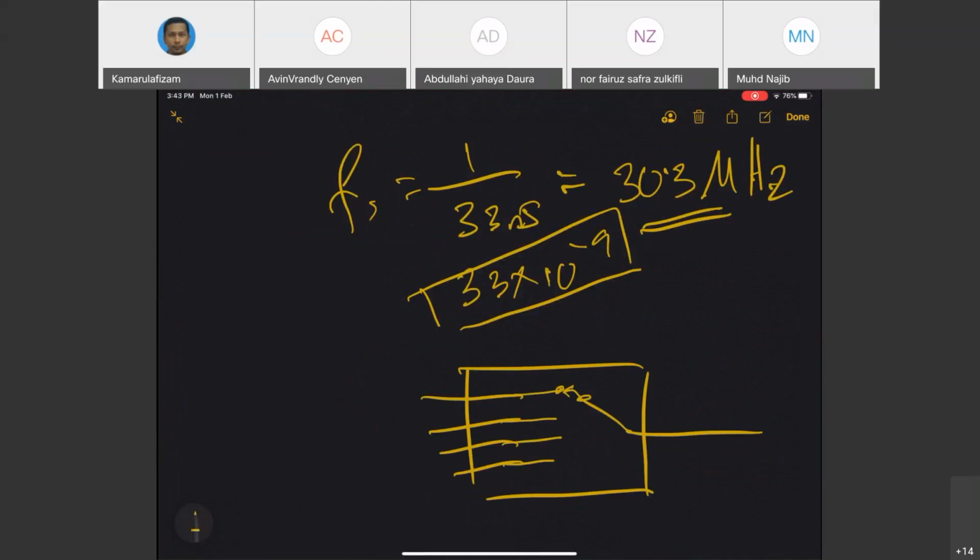In IC design, there are leakage currents, so you must expect the information from this line actually leaks to the adjacent line, depending on the information given in the datasheet. In this case, you are having something in nanoamps. All right, from here, for example, if your current is 4 milliamps, you must expect that the current is leaked by a few nanoamps to the adjacent channel.